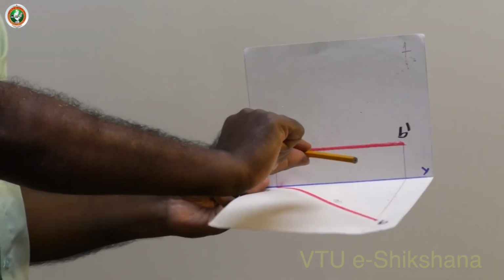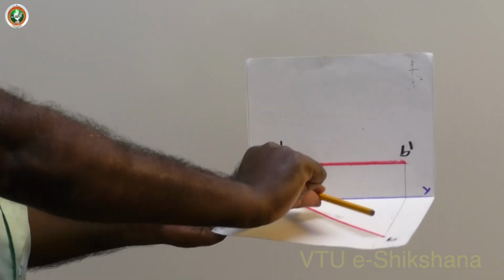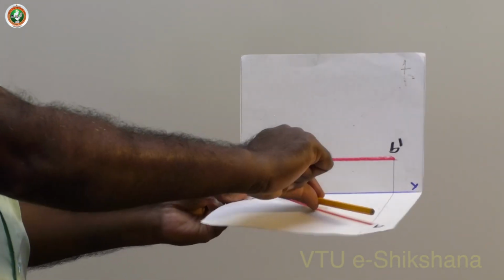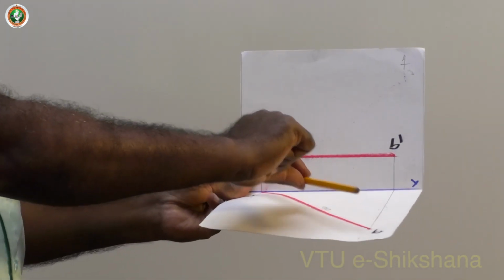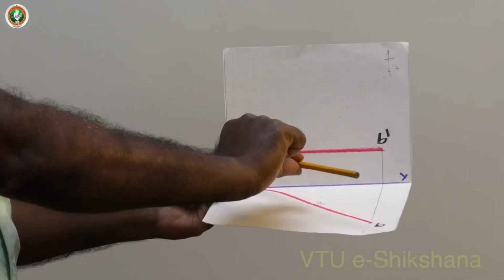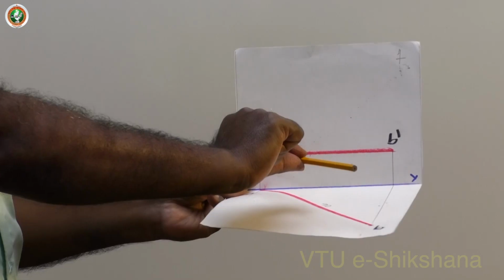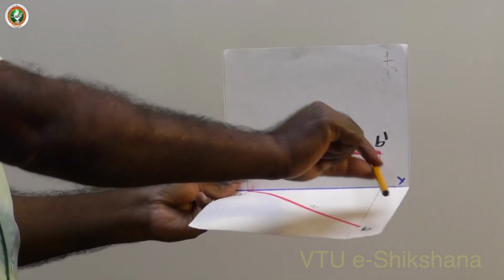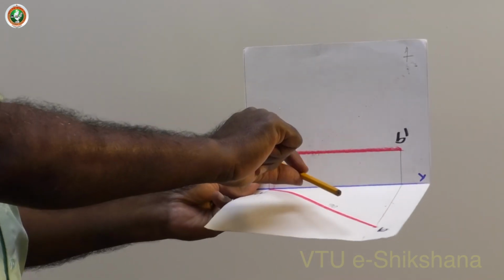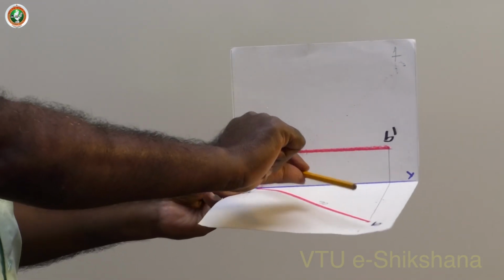So the projection of this line on HP is true length, that is AB is the true length. Again the projected length on VP is apparent length, because this is inclined at some degree to VP, the projected length will be less. Suppose this is 80 mm, this is around 60 mm, all depends on the angle.